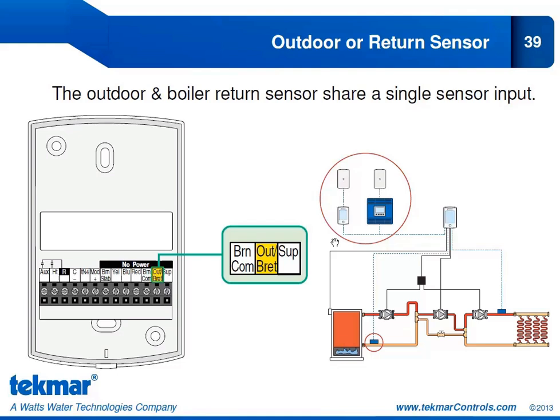So in the system menu, this is where you will set it up if that terminal is connected to an outdoor sensor or a boiler return sensor.